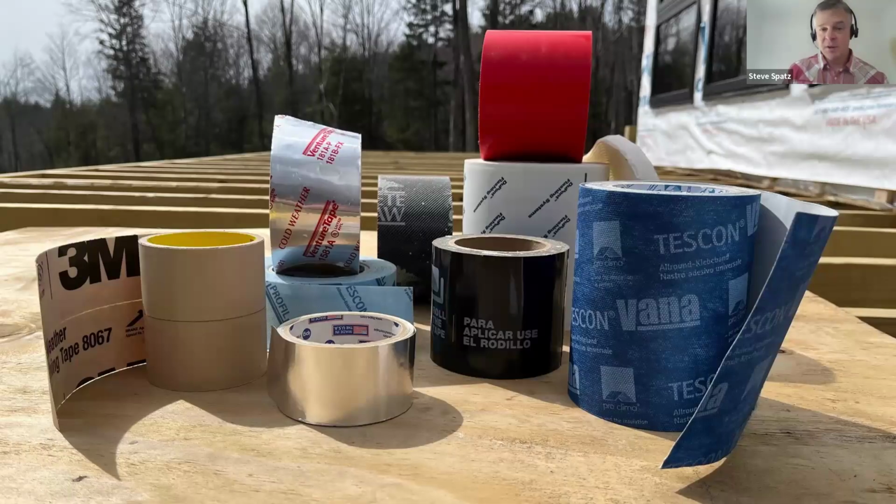So there's a lot of tapes on the market now. This is just a small smattering of what my collection has. There are multiple types of pressure sensitive acrylic tapes and other types. Really what you should be focusing on when using tapes as an air sealing component is that pressure sensitive acrylic type. Do not expect that a house wrap tape, clear cellophane house wrap tape, is going to stay adhered to the substrate and last over time and create air tightness. You really need to roll it. If it needs pressure, then you know you've got the right kind of tape for the durability.